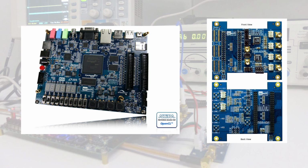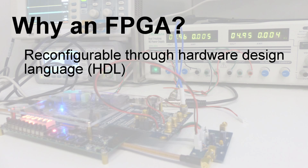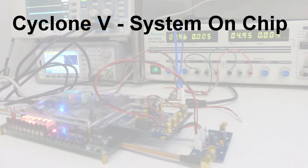We decided to implement the system on a field programmable gate array, or an FPGA, in conjunction with the Terasic ADDA daughter board, which allows for analog to digital and digital to analog conversion. The reason for using an FPGA is because it's easily reconfigurable for our needs, and we don't have to print off a new circuit board each time we want to design the next component. This allows us to actually pipeline our hardware in logic, and it allows us to estimate our latency very easily. The FPGA that we've used is an Altera Cyclone 5 SoC.